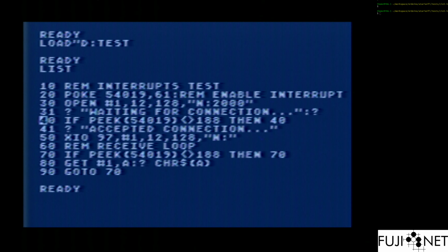Once this is done, the value will clear itself from bit 7, but bit 0 will also be zeroed out. So if you want to check for that interrupt again, you have to reset and re-enable that interrupt. This is not a behavior of the operating system, but a behavior of the PIA itself, acting as a mechanism for acknowledging an interrupt and pulling it back up again. It kind of helps you along in that way.